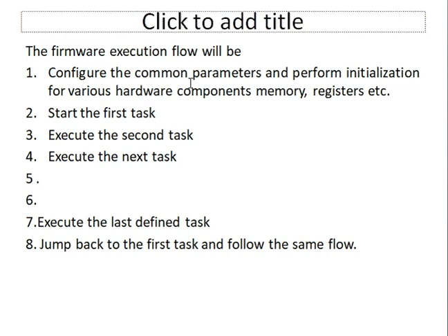The pins you connect to the hex keypad need to be set as input, and the pins you connect to the LCD screen have to be made output, since you are sending information to the output peripheral, whereas for a keypad you are reading the data from the keypad onto the microcontroller. So configuring your pins is essential.